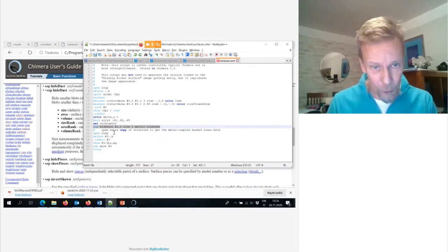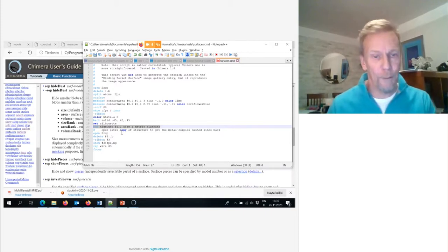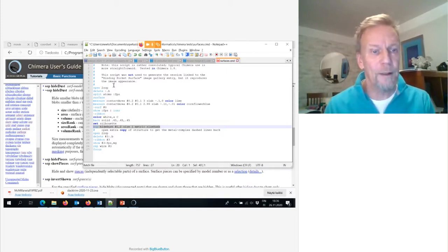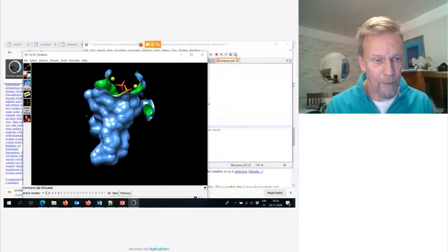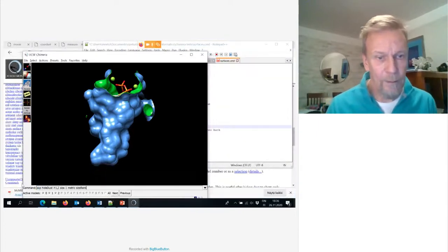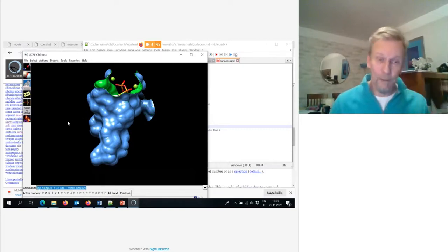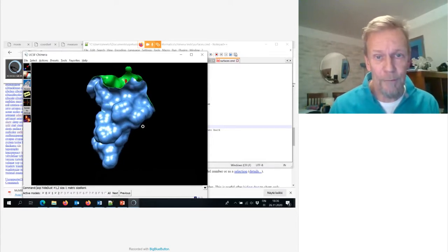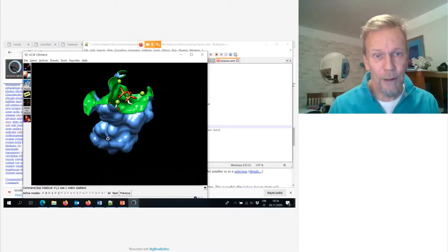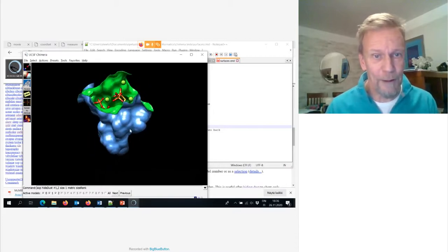So we are doing this hiding of dust for objects 1 and 2, which are the patches created by the measure surface area tool. And if you observe the loose pieces here, as expected, they disappeared, and it seems that there was a tiny bit even here on the side. So this is nice and fairly clean now.